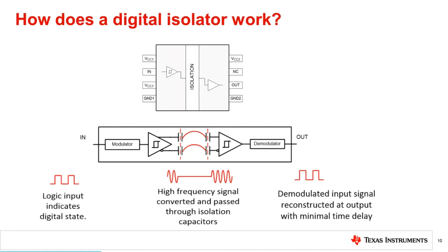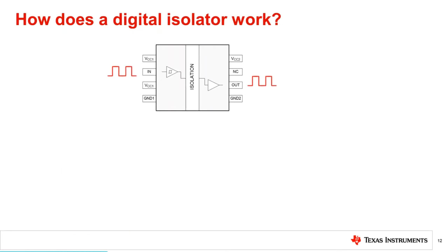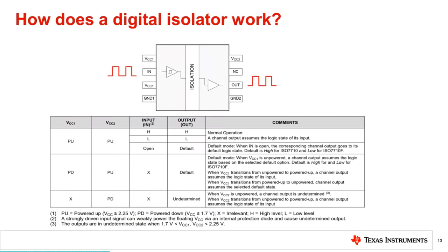As mentioned earlier, digital isolators are most commonly used with isolated power supplies and separate grounds, which is also useful in preventing ground interference and noise currents from power supplies. Digital isolators use CMOS or TTL logic switching technology and have specified default output states of high or low that can be found in the device functional mode section of the datasheet like the one shown here.